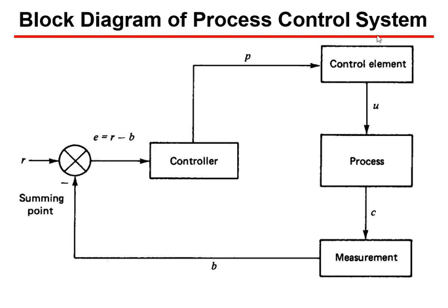Whatever the control element will do, any act, depends upon the output given by the controller. That is very important. The control element is just an interface between the controller and the process. Whatever signal is given to the control element by the controller is given to the process to get the desired output. That is very important to understand. So the most important concern about the design is this controller.